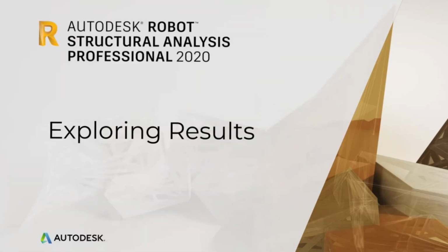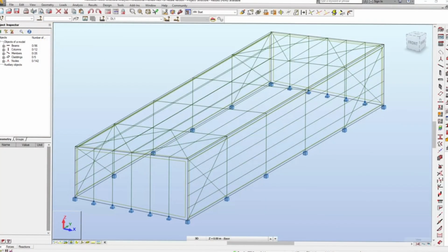After a modeled structure is defined with applied loads, you can run several different analysis types on the structure. In this example, a linear static analysis will be run. With the model open, from the text menu, select Analysis, Calculations.